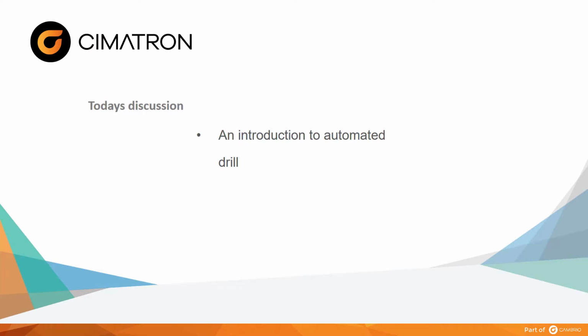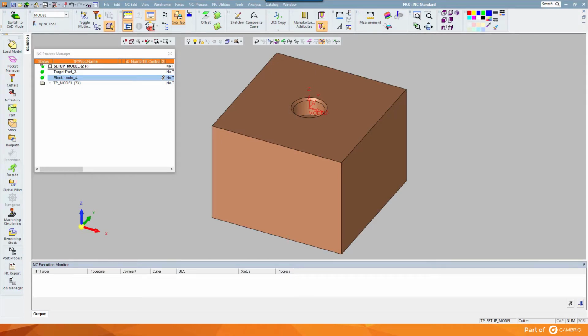Automated drill has three basic functions. The first is to group holes together that are the exact same size and shape. The second is to build, contain, and store drilling sequences. And the third is to automatically fit or match saved sequences to grouped hole geometry based on ranges the user allows.